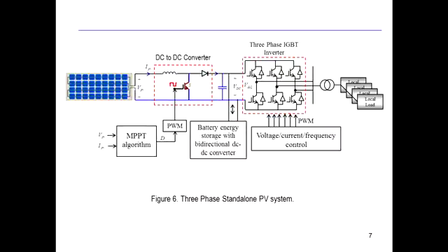This is another slide where this is still a local load, but three-phase. Again, a boost converter, increasing the DC supply voltage here to a higher level, which is what a boost converter provides. And then the inverter supplies the local load, and if the local load doesn't require all the power that is available, it can go to the battery. If we don't have a battery, for example, in households, we still don't have battery systems. So if we don't have batteries, then we don't convert solar energy into DC power here.